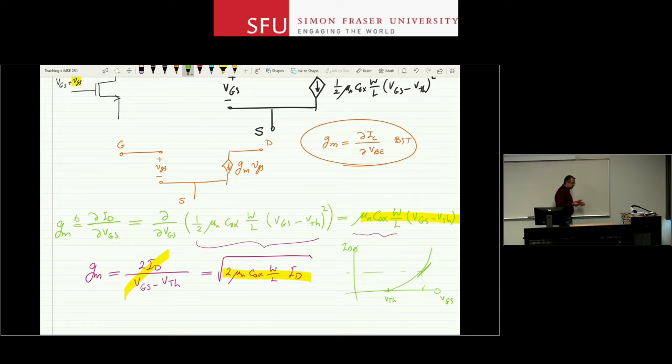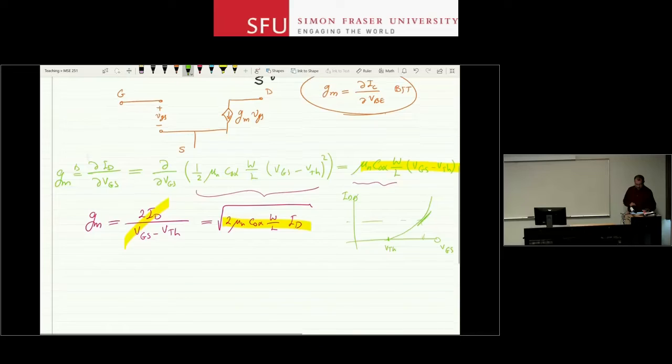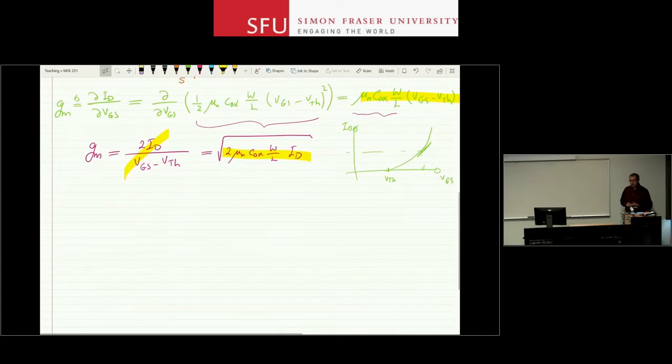And good news here is that for PMOSFET, similar to what we discussed for PNP and NPN, the small signal model for a PMOSFET is exactly the same as what you have for an NMOSFET. So that's good. For PMOS and NMOS, you do a separate DC analysis, but once you get to the AC stage, basically the two are the same.